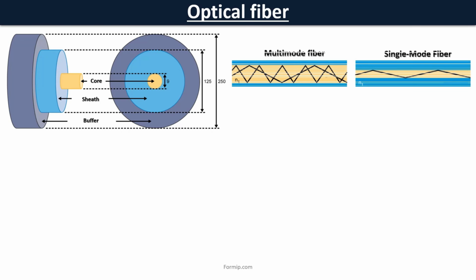Now let's look at the 2 types of fibers, single mode and multi-mode. The difference between the 2 is the ability of the fiber to send light over long distances at high speeds. In general, multi-mode fiber is used for shorter distances with much lower speeds than single mode. For communication over long distances, we'll see single mode. In the image that represents the 2 modes, we see that the main difference is the size of the nucleus. Single mode fiber costs more than multi-mode.